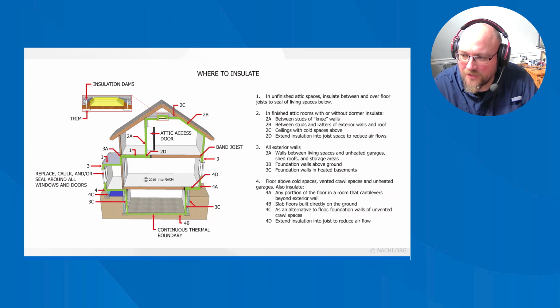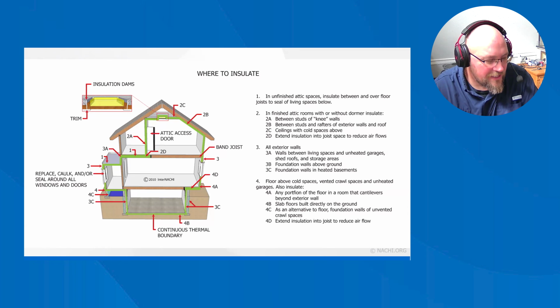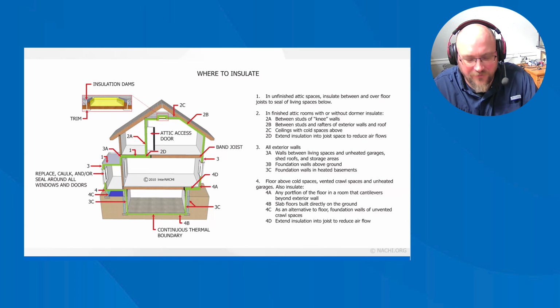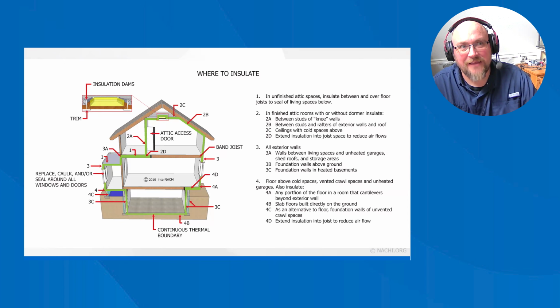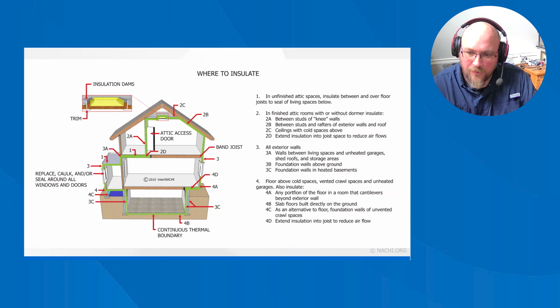Here's a quick example of why you should have this checked, or you could make a recommendation to your client or on your own home. If you do add insulation in your home, it was very common practice, especially in my area, that if an electrical junction box was added inside of an attic, they would leave the cover off, so they would not put a cover on.